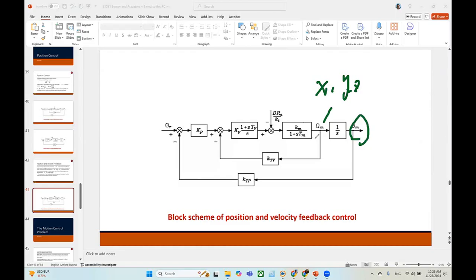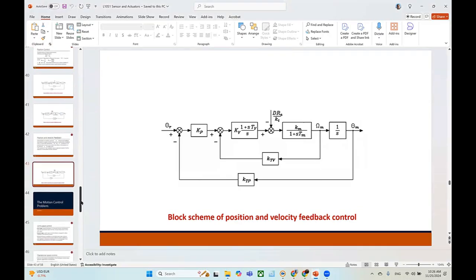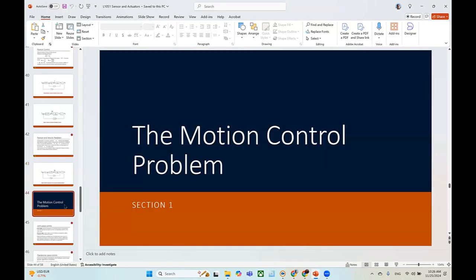Displacement is the integral of your velocity. So here, this one may be velocity, this one is integrator, okay? And you provide the control back to your loop. So this loop actually has both velocity and also the position control, okay? So basically what I want to say is that you build your feedback loop, and then convert it to a differential equation, and then those differential equations are transformed to Laplace transform, and you get this model.